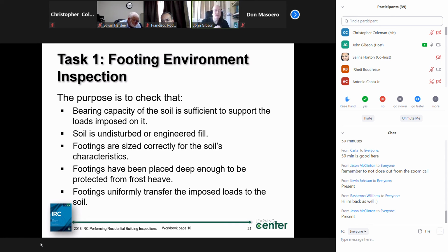And I'm going to look for the lowest points of ground I find within those 6-foot distance. So if it's all straight against the building, then it would be at 6 feet out would be my lowest point. Yet if I have any kind of a swale in here, it may be some point inside of that 6 feet that I get the lowest point.